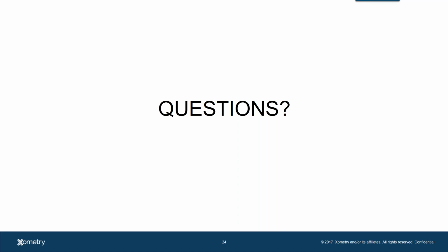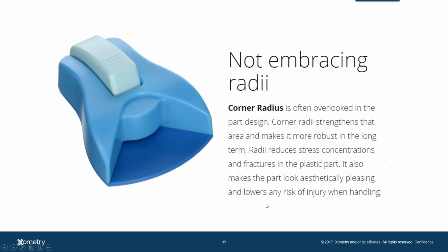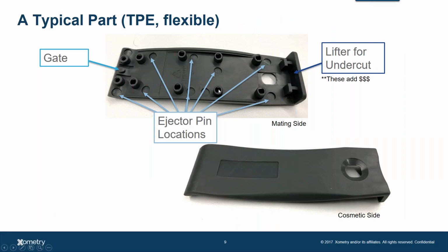Another question here. How can you determine and make sure how many ejector pins you will need in order for the part to eject properly? That's from Jessica. Well, it's a loaded question. Just looking at the part geometry, if you can imagine anywhere it's going to stick inside of the tool, you will need some type of ejection. There's many ways to eject a mold. You've got ejector pins, ejector sleeves, stripper plates. There's so many things you can do to a part to get it off your mold. But once again, it depends on the part geometry and how big it is.